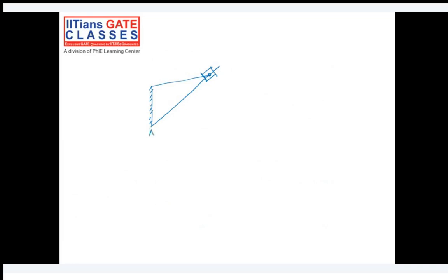Can you tell me what this is? Slotted one. No, it's a second inversion, where the crank is fixed, and we use it in the Whitworth quick return mechanism. Okay, it's the slider crank second inversion. So in this case, how will the velocity diagram look?